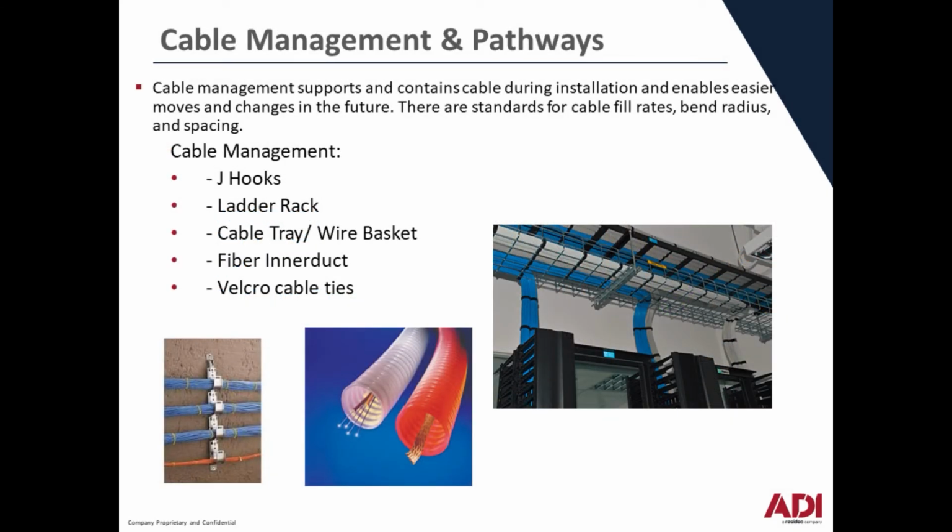Next, we're going to look at cable management and pathways. Cable management is often overlooked as a key component to the cable installation. Cable management is made up of J-hooks, ladder rack, cable tray and wire basket, and fiber interduct. The cable management supports and contains the cable during installation and provides easier access for future moves and changes. There are key standards that need to be followed when installing cable management. Those include cable fill rates, bend radius, and spacing.